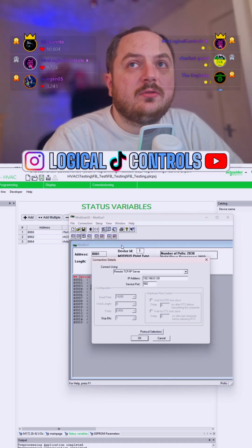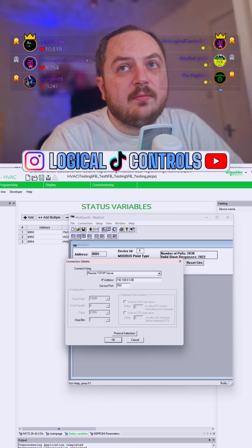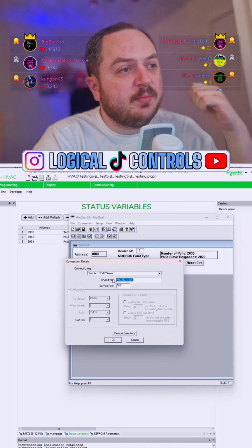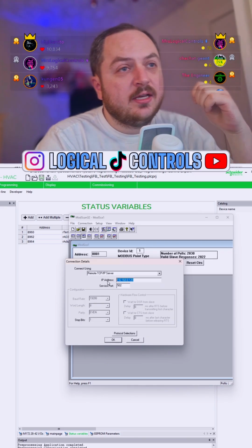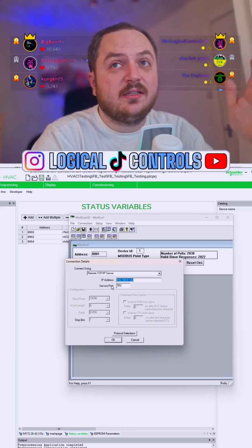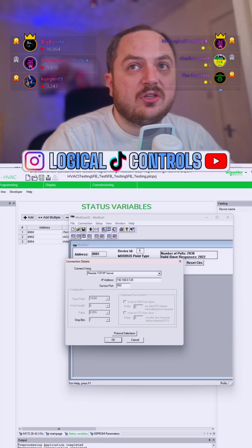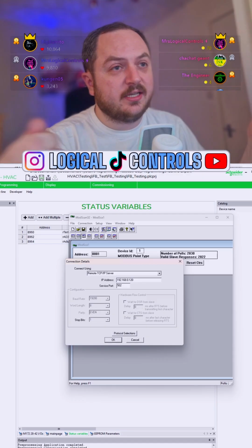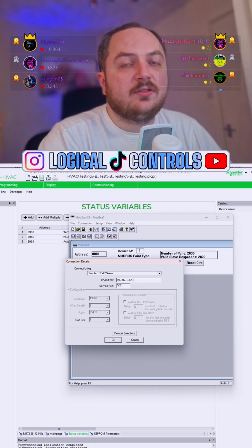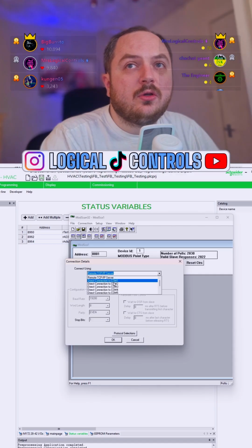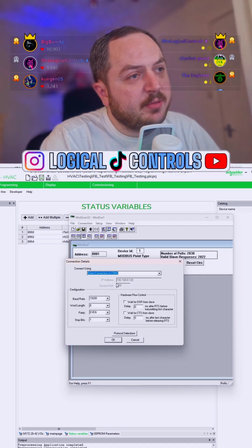So when I go to connect, I'm putting in an IP address. So I'm looking for that Siemens PLC that I've got by typing in an IP address. Modbus TCP is super easy, straightforward to set up. There's almost nothing to go wrong. You just need to get the IP address right. Make sure they're connected together with a Cat5 or Cat6 or something. It's really easy. If I was to look on serial, then you don't have IP addresses anymore.